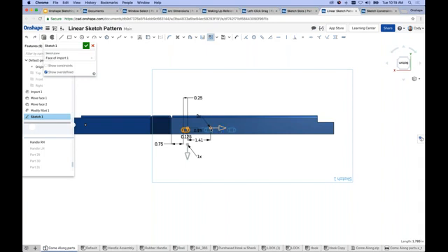Another one that I would point out, not many are aware of, you can also grab this point on the manipulator and move up, or down. By default, it's going to assume that you want to go horizontal with the x-axis, for instance. But what if you wanted to align your pattern with an edge of the part? Well, I'd move this close to that direction and then edit my sketch later to actually make it parallel, to define it afterwards. My point being, by default, it's going to assume that you want a horizontal or vertical pattern, but you don't have to. You can make those changes. You can grab and drag and dynamically change things around as you see fit.